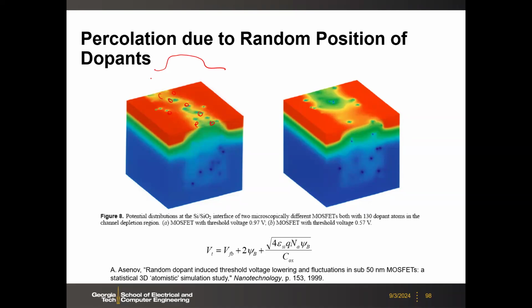If you think about source, drain and gate, you have NPN. If you have a P-type dopant in the channel, effectively you create this PN junction, so you have this barrier. That's why electrons will be flowing over this barrier. And as we discussed before, when you apply gate voltage, you lower the barrier. Therefore, the electrons can flow over.